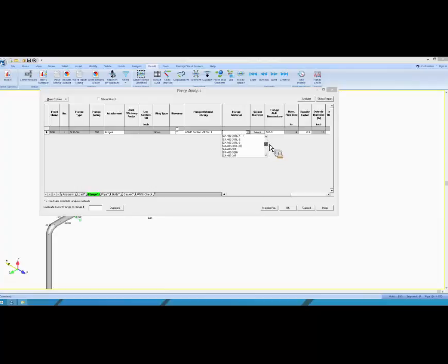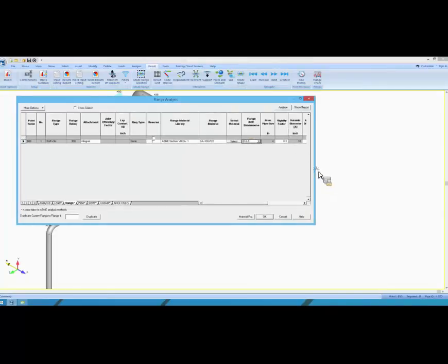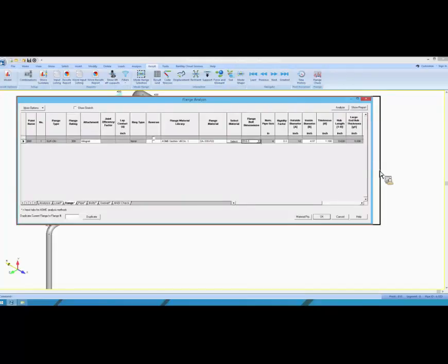For the flange material, you can either press the select button or simply look at the drop down. The pipe material, if I can recall, for this pipe was SA335, so I would want to select a similar pipe flange material. The flange bore dimensions are coming in from B16.5, and then there is a rigidity factor required for the rigidity criterion, and the rest of the data is automatically picked up by the program once a selection is made for the flange bore dimensions.